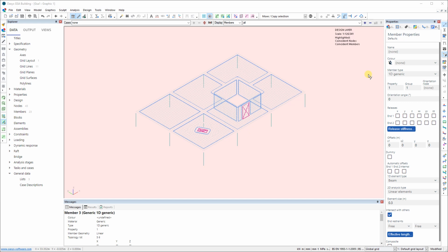But before we do anything else, the thing I would always recommend is that at each stage in building an analysis, you try to actually run the model just under its own self-weight, for example, just to be sure it actually works. There's nothing worse than spending a huge amount of time building a big analysis model, getting to the end, trying to analyze it, and finding it just doesn't run, and then having to spend ages trying to understand why that is. So what do we then do?